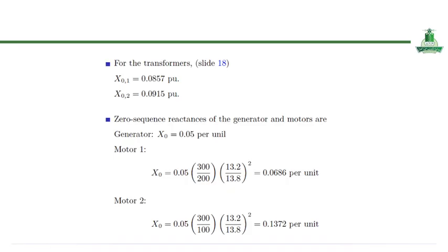This slide focuses on determining the zero sequence reactances of transformers, generators, and motors in per unit values, which are essential for fault analysis, especially under unbalanced conditions.